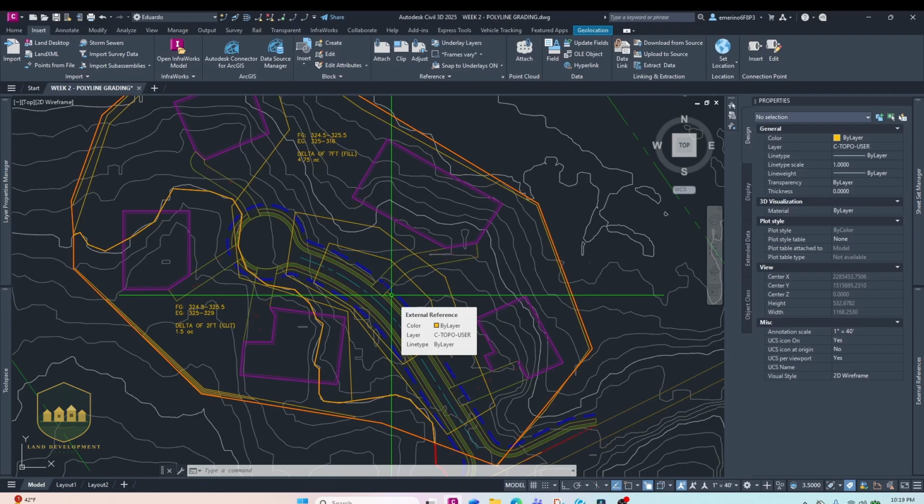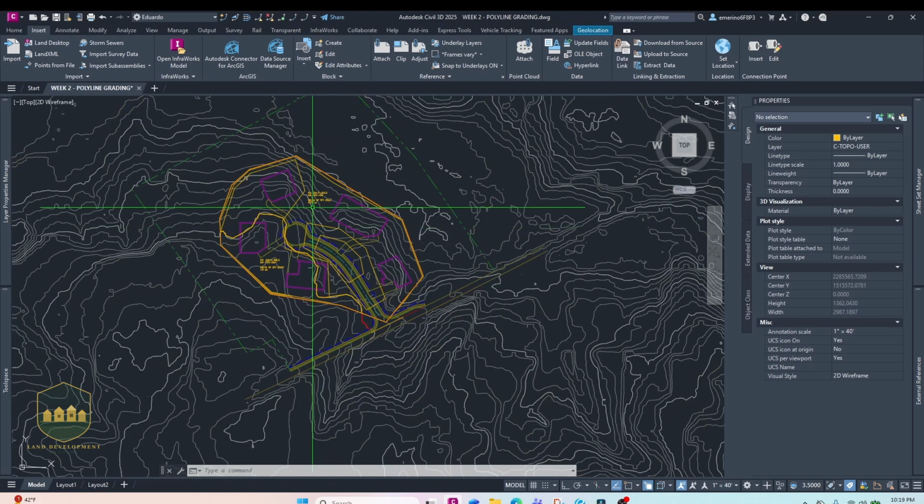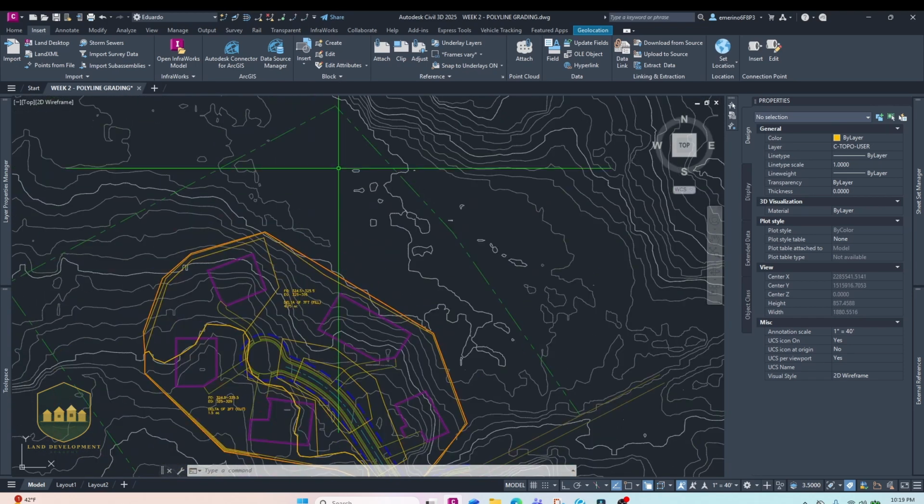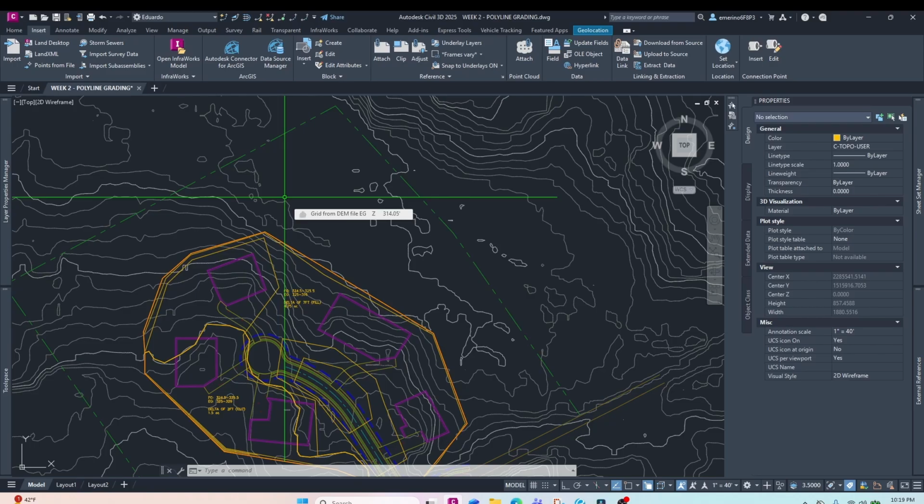Also, it's a lot easier, if you have extra dirt, to spread it around and add fill in some areas. And this is also not accounting for a stormwater management pond that is just a ginormous hole in the ground. So that's also going to generate more cut. So you do have some other options if you're slightly off balance.